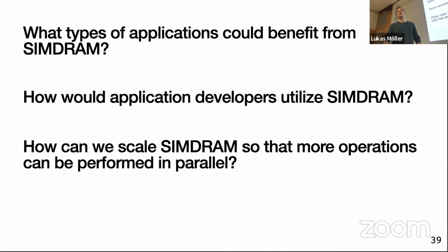But the SIMDRAM control unit could become one of the bottlenecks there at some point. Even if you have multiple SIMDRAM units, wouldn't the bus be the bottleneck then? Because you have to issue multiple control signals at once. Yeah, sure, that would also be a problem, but each of those triple row activations would only be around the size of a write or a get, right?